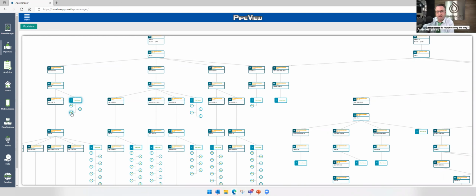Yeah, and there are often cases where a zone has priority, either because there's new seed going down, or it's a pond fill. There are numerous reasons why a zone would have a priority. And if it's set up correctly in the schedule with priority number 1, that means if anything else is running, that particular schedule goes to the top of the list and waters.